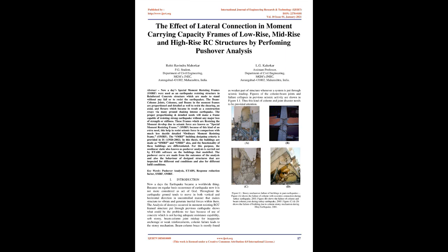resisting frames, SMRF. Because of this kind of extra requirement, they help to resist seismic force in comparison with much less ductile detailed ordinary moment resisting frames, OMRF. The SMRF building design criteria is provided in IS 13920:2002. In this thesis, the buildings are made as OMRF and SMRF also, and the functionality of these